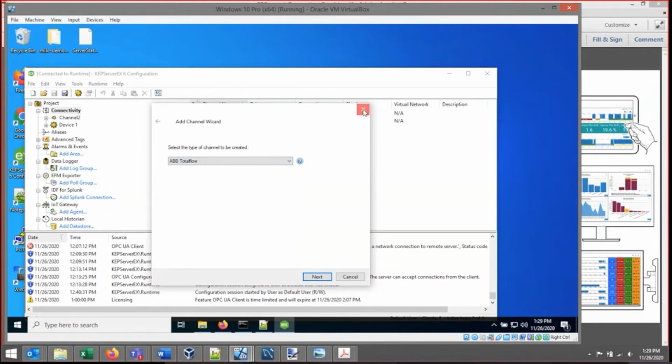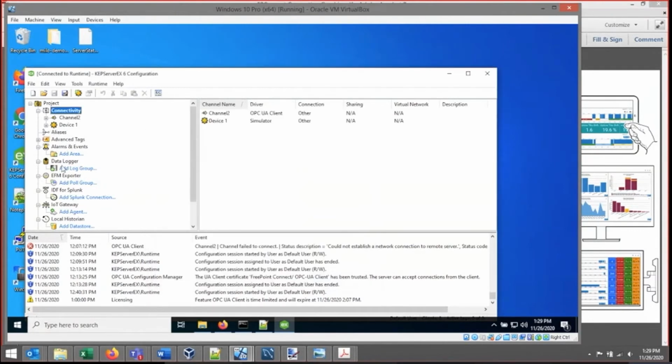Not only does Kepware talk to all of them, it presents them in a list in its interface that says, here's machine 1, here's your Mazak 12, here's your Heidenhain controller. It doesn't matter what the machine is, it just presents a list in here of all the machines. Kepware takes all those different languages and conforms them into one standard, and then we can access all of that data because we talk OPC UA.